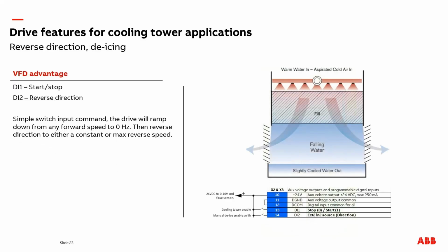In cold climates or winter operation, ice buildup may form on the outside of the air intakes. If no bypass valve is included to direct water flow to the basin or dampers to close the air intake louvers, reversing the fan direction can move warm air back out to the louvers to melt ice before returning to normal tower operation. Tower fans without a variable frequency drive won't be capable of this reverse direction option, requiring other forms of ice prevention.